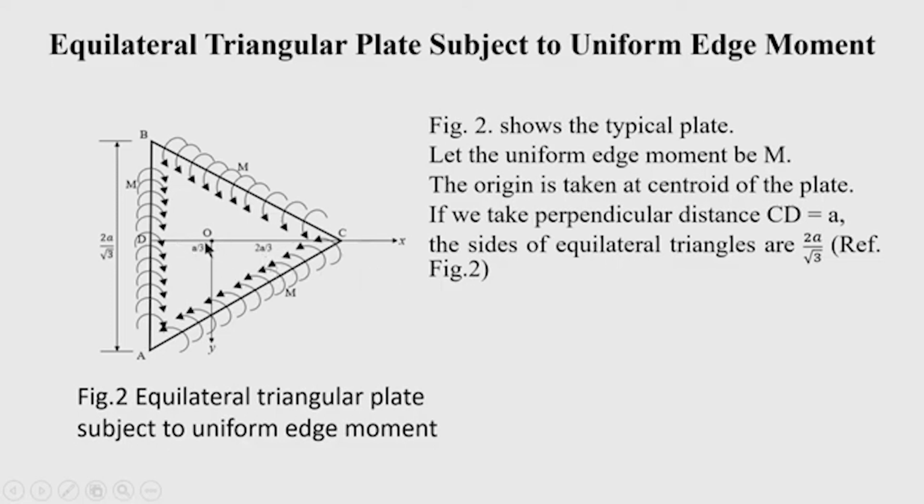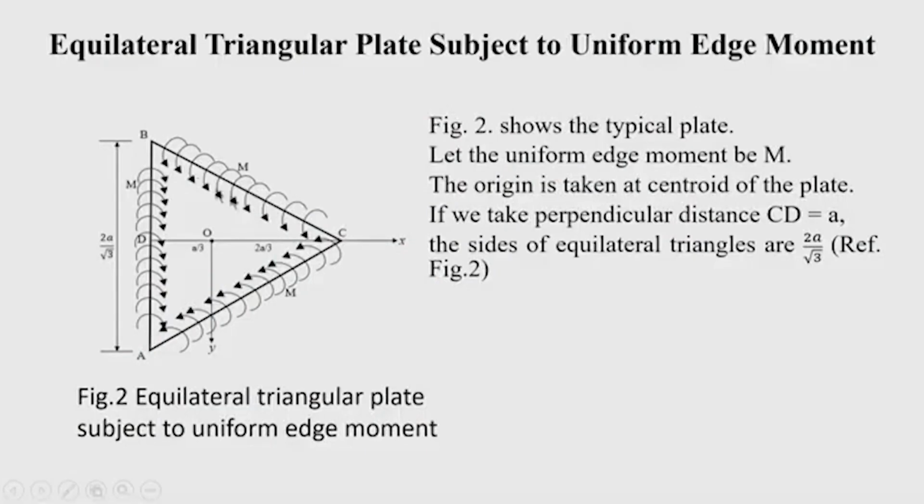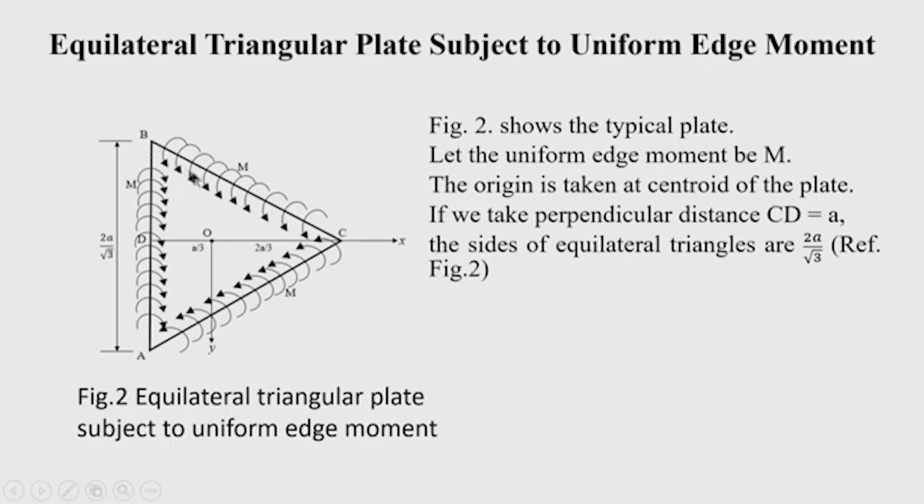So, after getting the CG, now let us formulate the problem. We can see that at the boundary, since it is simply supported, again we are taking this plate edge as simply supported, because we are dealing with only the simply supported condition. In the simply supported case, along the boundary deflection is 0, that is obvious, and another condition is that bending moment is 0. Bending moment 0 means, here this edge is inclined, it is neither parallel to the x axis nor parallel to the y axis.